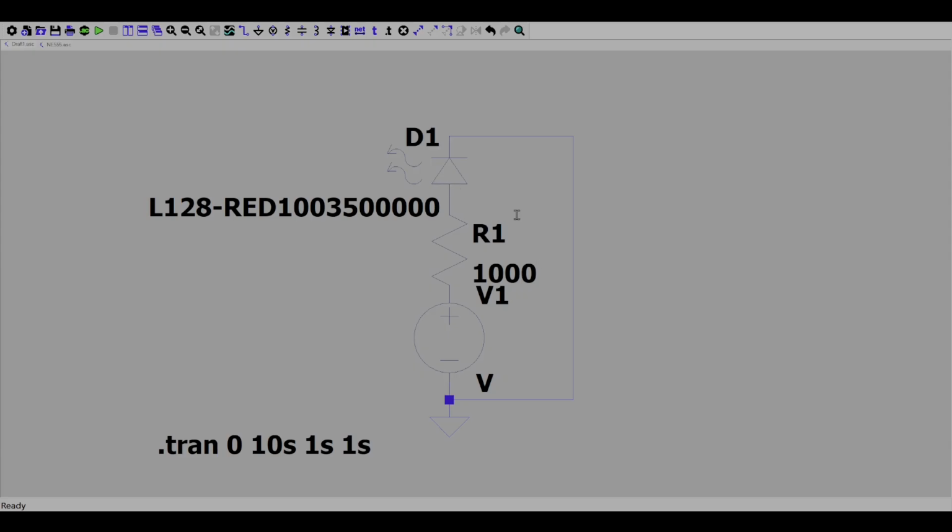I don't know, DC sweep. Say name of this first source to sweep, I guess. Linear. Start a value at 0. Stop at 5. Go by 1. Let's see what happens.